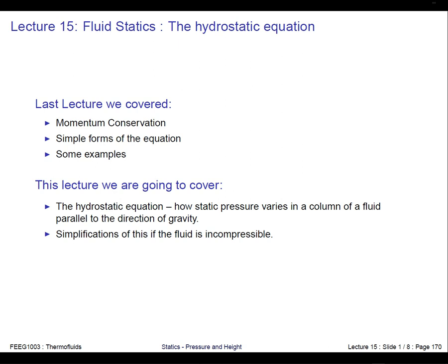One of the reasons for introducing momentum conservation last week was to provide a context for introducing hydrostatics. Normally in fluid mechanics, statics is taught separately from momentum conservation, but the best way to understand statics problems is to imagine a momentum problem where there isn't any momentum, and you still have to balance the forces on a volume of fluid because it's static, it's not moving.